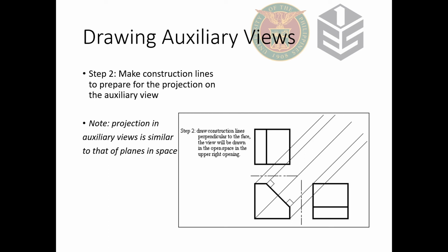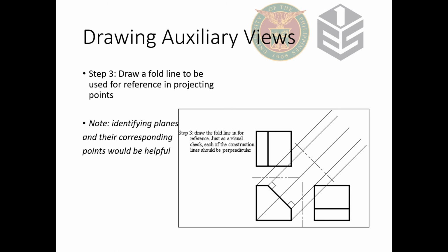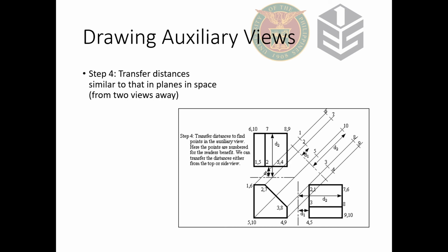So we draw a fold line, and at this point you would want to identify the planes that you have and all the points that each plane has. It will help you in projecting in step 4. So remember, when projecting points, you have to consider two views away. When I say 2 views away, this distance here corresponds to the distance here. So 1, 2, 2 views away.